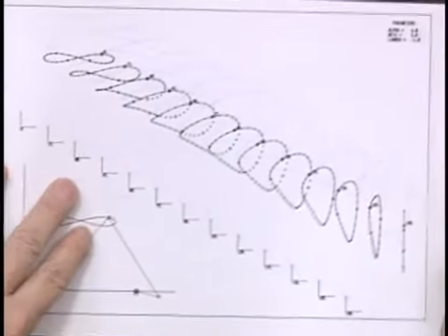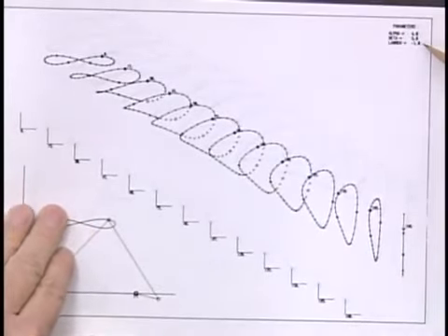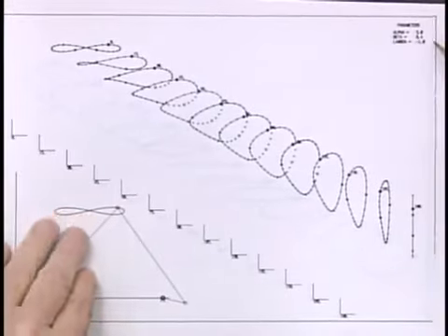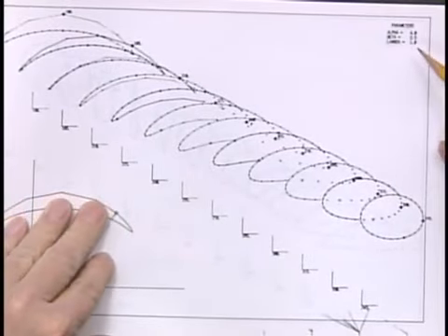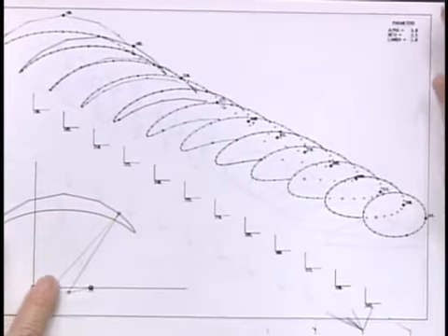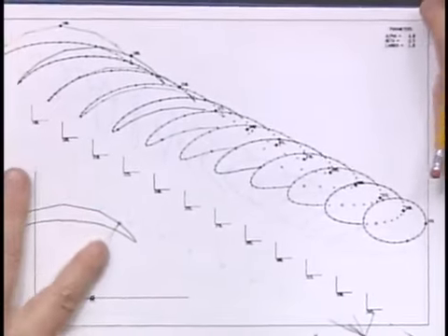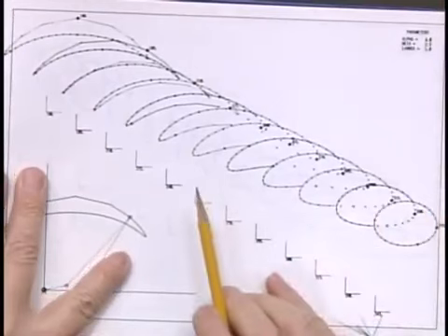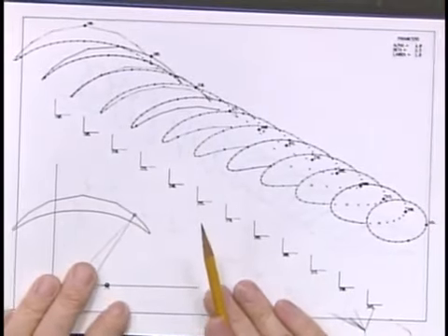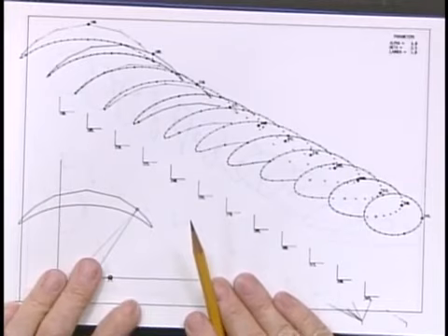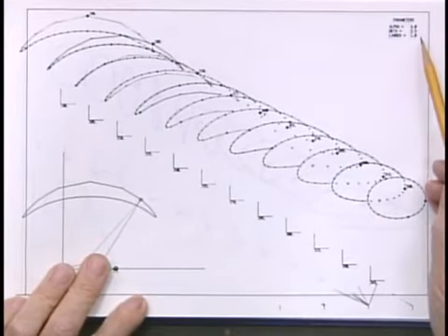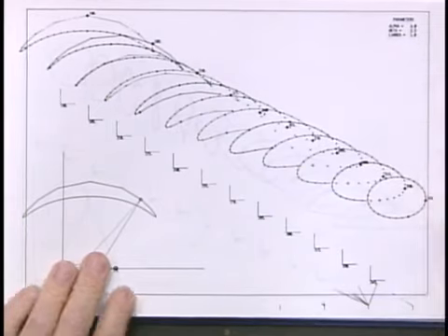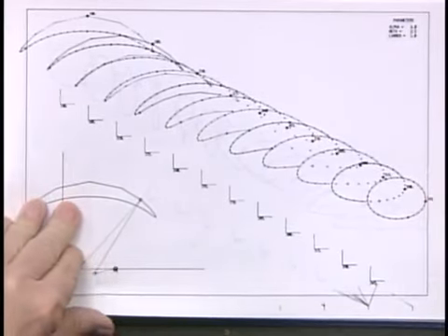Okay, I'm going to flip through this to get to some more interesting looking curves. I'm still in the -1 gear ratio department here, and that doesn't have very interesting stuff. It looks too much like a 4-bar linkage. Now I'm in +1. And as I show you in Design of Machinery, at some point you can actually generate the same coupler curve that a 4-bar linkage generates with a geared 5-bar linkage that has a +1 gear ratio. This is in Chapter 6 under the topic of cognates.